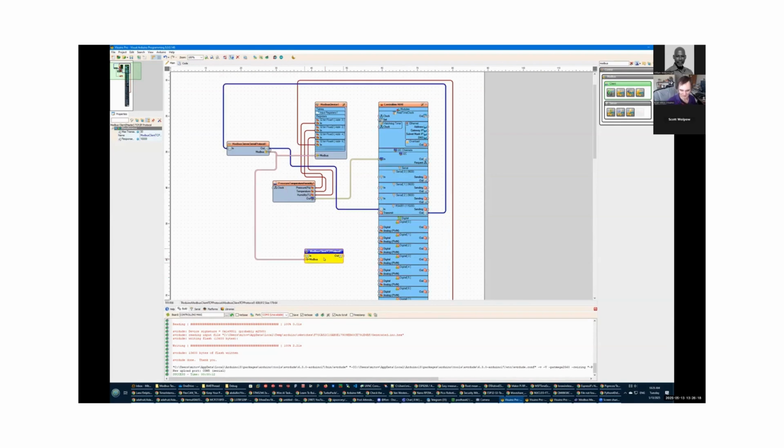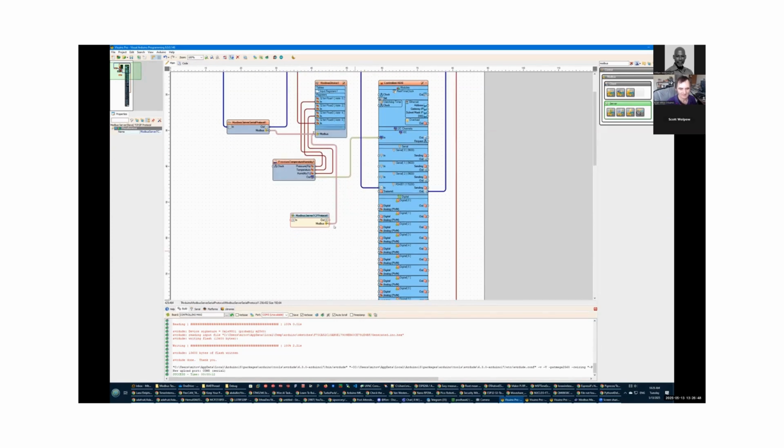Does this program the Arduino? The device is an Arduino-based device. Does it program it? Yes. So in other words, once you do this, could you unplug the Arduino from your computer and bring it out to the field? Yeah, it's ready. You can put it in the field immediately. And therefore, it would know that once the temperature hits a certain level to turn on that. Yeah, and you can control that with Modbus, as I already demonstrated, and you can monitor it with Modbus.